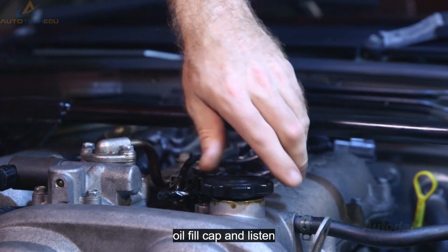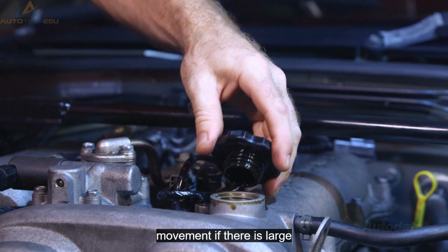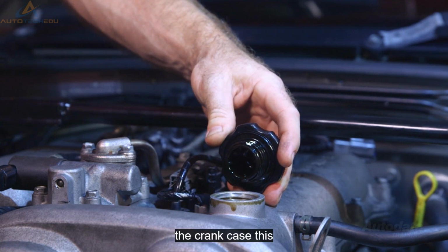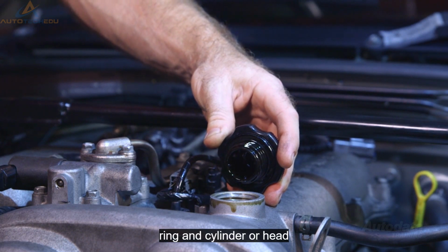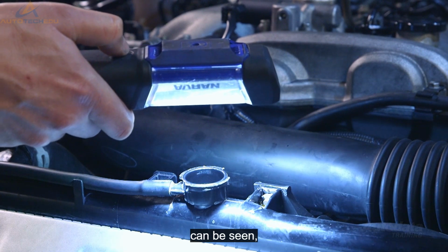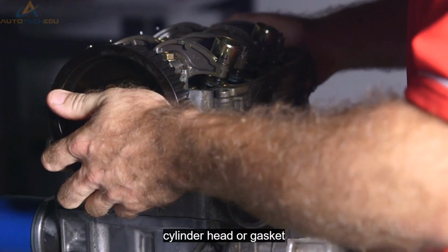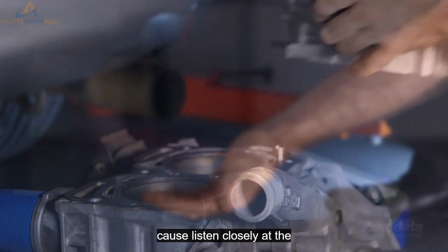Remove the engine oil fill cap and listen or feel for any air movement. If there is large flow here, then air is leaking into the crankcase. This could be due to piston, ring and cylinder, or head gasket damage. Remove the radiator cap and watch for air bubbles. If these can be seen, then the compressed air is entering the cooling system. Cylinder head or gasket damage is the most likely cause.